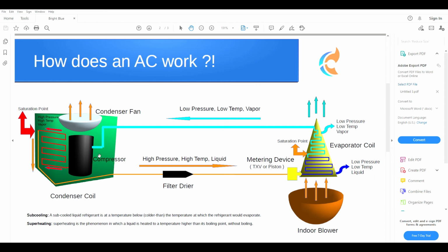Usually it's 350 to 400 CFM per ton. So you have a 2-ton or 2.5-ton. For a 2-ton, you will need 800 CFM at 0.5 inches water column static pressure, and for a 2.5-ton, it's 1,000 CFM and so forth. So you always have to adjust that airflow. Different furnaces and different air handlers have different settings.